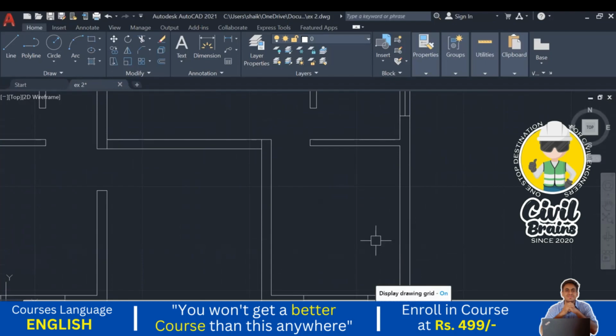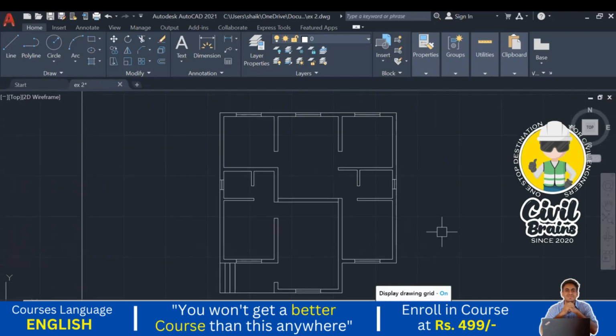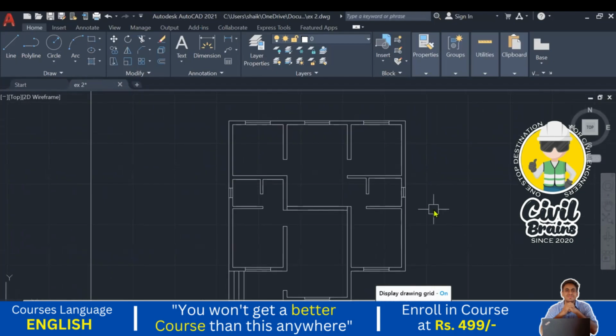But here inside we will not show it, because we are considering it is at the sill level. If it is at the sill level, then above the plinth there will be flooring. If there is flooring, then this will not be visible. But outside there is no flooring, right? That's why we need to show that one. So I will go to the offset command and take 0.11 as a plinth projection or plinth offset.